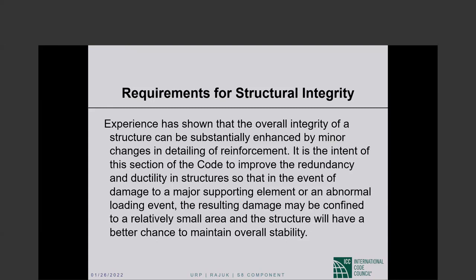In the best of circumstances, it can be a compression lap splice. If you look at the picture that I showed you, the dowel has to lap with the lower column bar and with the upper column bar. The lap lengths have to be sufficient according to the example we went over yesterday, column bar splices. So that's what you will have to provide.